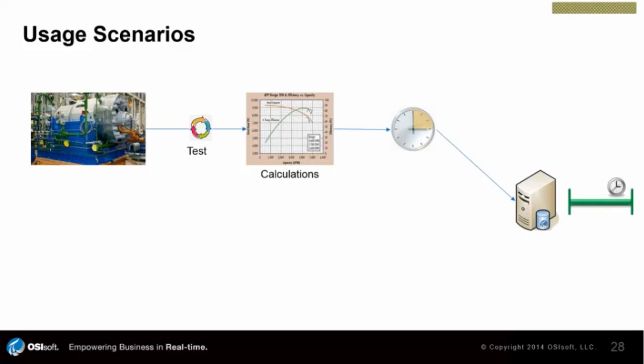Once the calculation starts running, you want to store the results into the Pi server, either as time series data or as events. When you design and build these new calculations, oftentimes you're going to want to apply these calculations to historical data that you have in your system. We call this backfilling, and backfilling is one of the key features that we built into version 1 of this new calculation engine.